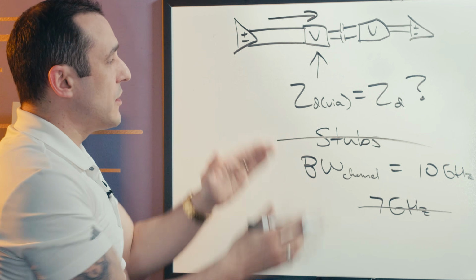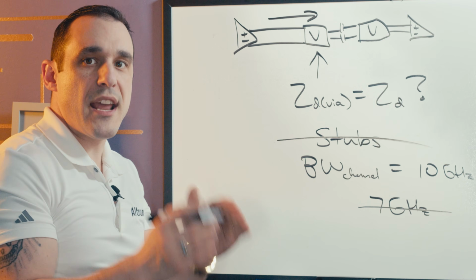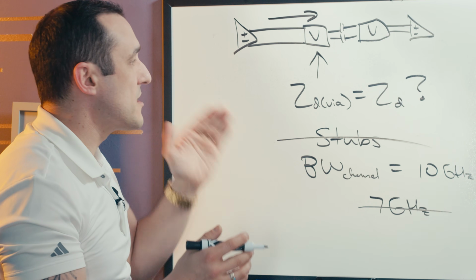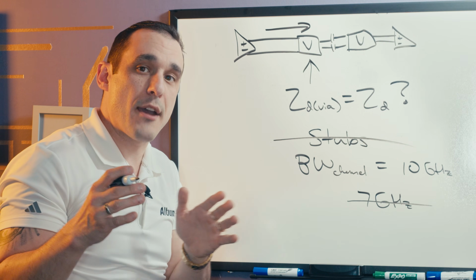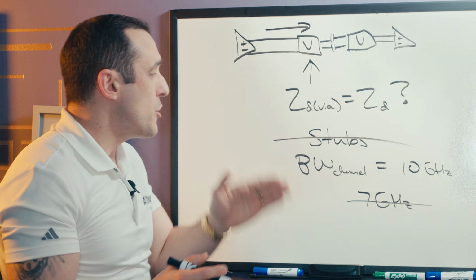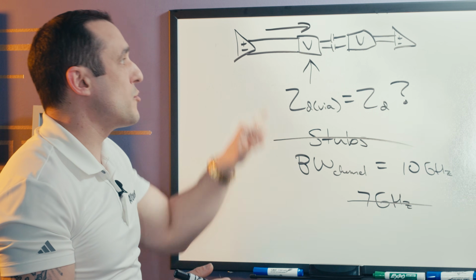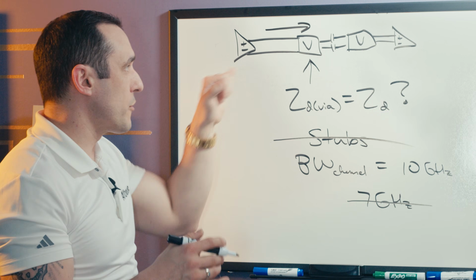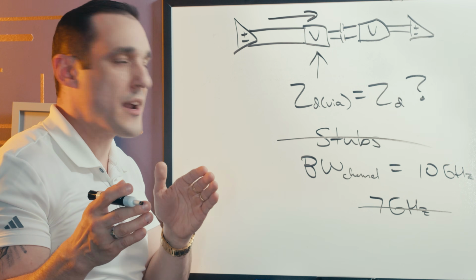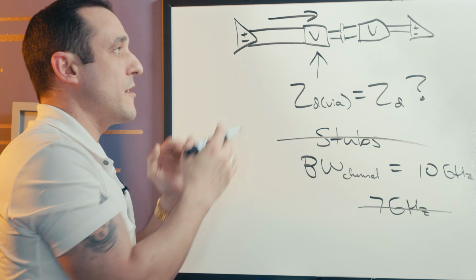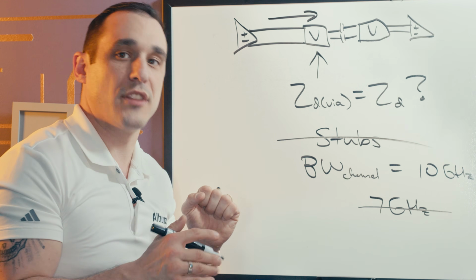So this idea of eliminating stubs in order to eliminate an impedance mismatch that produces high losses along this interconnect is consistent with the other takeaway that we saw looking at microstrips. You have to eliminate those impedance mismatches within the channel bandwidth in order for the interface to work. And if you do that, as well as all the other design points correctly, the location of the placement of these coupling capacitors is going to be much less important.